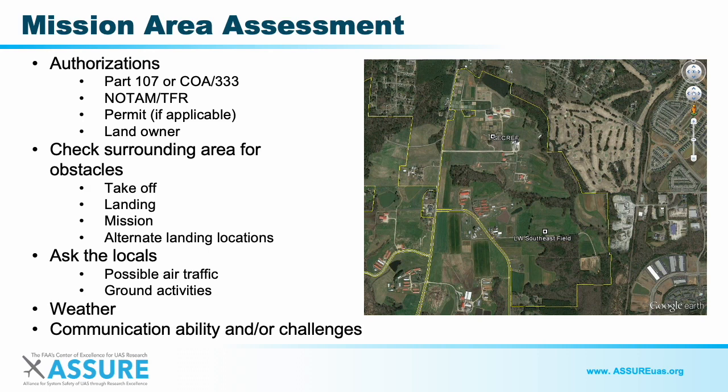Make sure to check the weather forecast. Lastly, there can be challenges as it relates to frequency transmission, which could impact your drone and/or controller. Take the time to learn about spectrum analysis and what could cause frequency interference. It is always a good idea to check your compass to see if it needs to be calibrated.